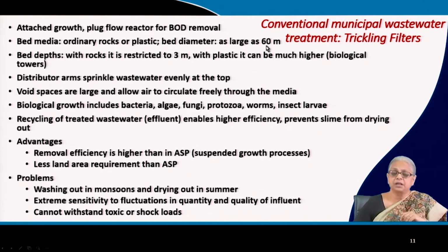The bed diameters can be anywhere from 30 meters to 60 meters, or even smaller. Bed depths are restricted. If you're using rocks and stones, the depth cannot be more than 3 meters. But with plastic towers, which are called biological towers, these can be very, very high.